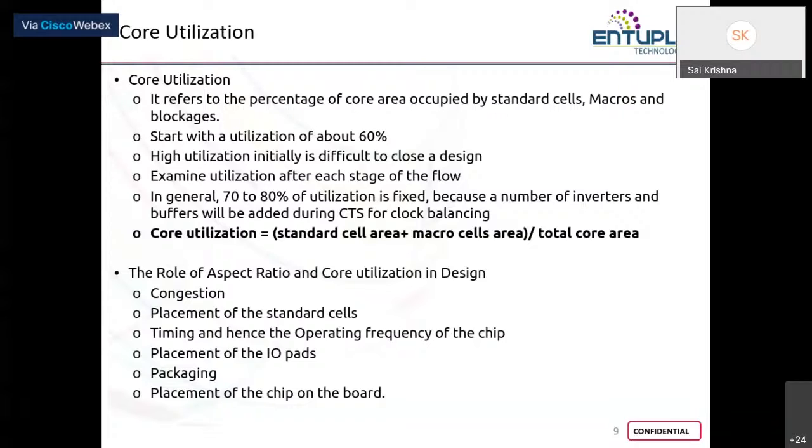So when you're dealing with a highly complex design, nowadays in the industry, it is a very common practice to add these buffers in the data paths. I'm talking about data paths, the path where the data flows, and I'm not talking about the clock.